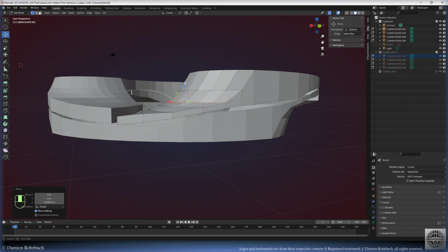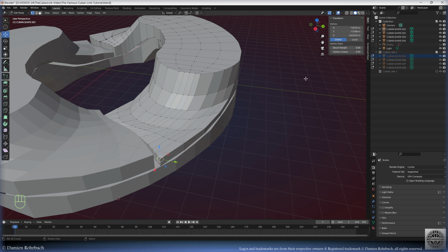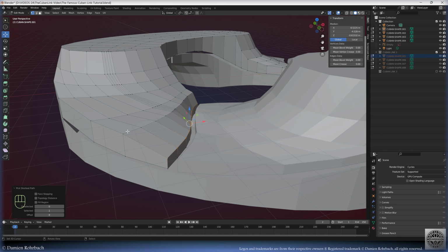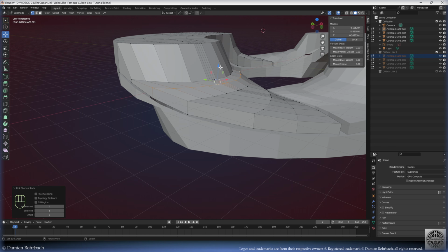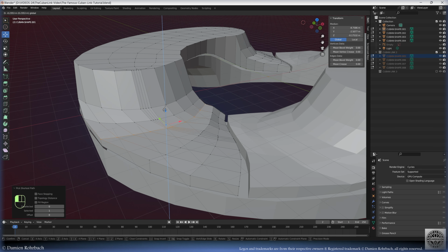So now that I have worked on one side, what I can do is the following. I can look up the global Z position like here, copy it, go to the other side there, enter the Z position with the Alt key pressed, do a paste, enter. Now I have the same thickness on this side and I can rearrange the rest of the other side like this. You can make it come down very steep and then continue with a nice smooth slope.